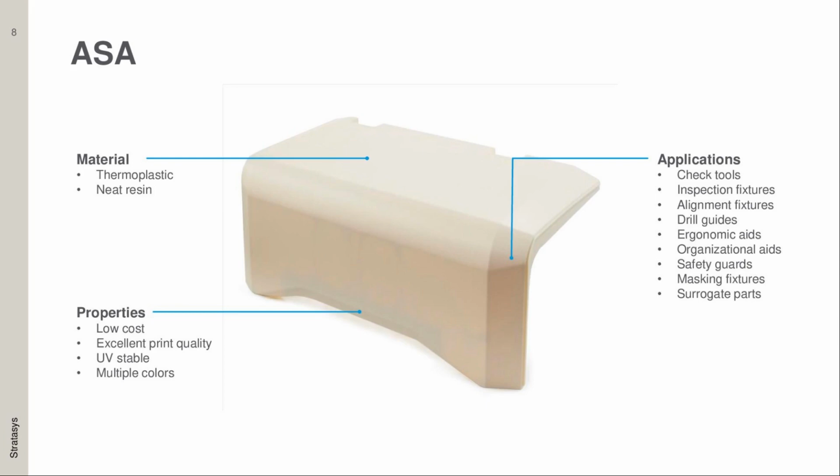So as we optimize our processes with Six Sigma and some of the other manufacturing optimization techniques, color coding is a big deal. So all of your drill guides can be blue, all of your inspection fixtures can be red, or you could just color code them based on the operator. So David's tools are green and Jacob's tools are purple, things like that.